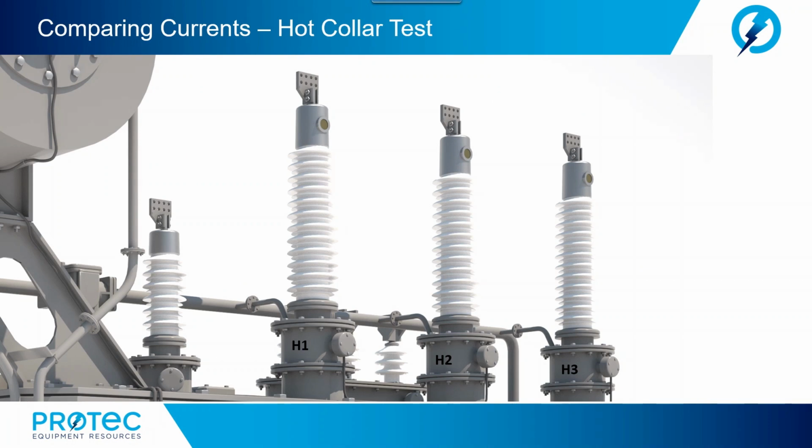So, let's bring this a little bit more into applicational practice. The hot collar test is a part of the procedure in the power factor testing of a bushing. When the power factor is done on a transformer, the test connections are on the transformer bushings, and the power factor test includes the transformer winding and the bushing.